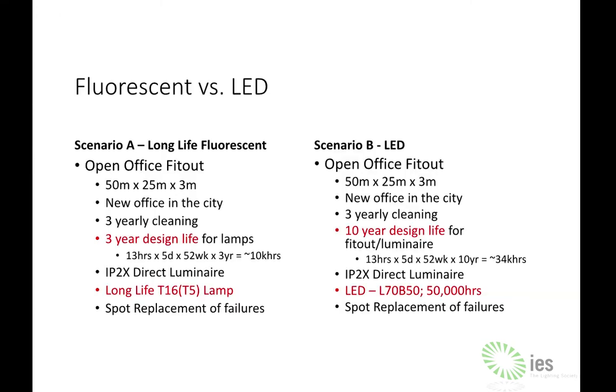But let's really get into the interesting ones where we compare a fluorescent versus an LED. An open office fit out, just like our old one, 3-year cleaning. The fluorescents, we get a maintenance contract out. We're expecting them to last 3 years. Every 3 years they walk through, give the luminaire a wipe down, give the lamp a wipe down, replace the ones that have failed. Whereas an LED, they just give it a clean down every 3 years, and otherwise the fit out's only supposed to last 10 years.